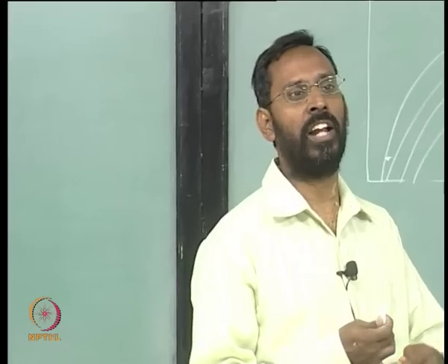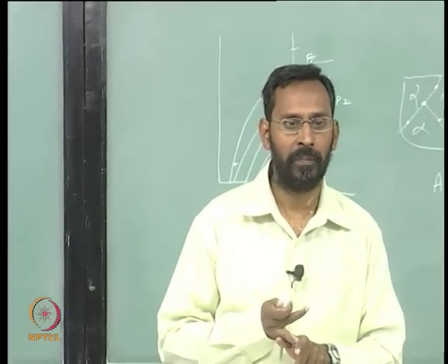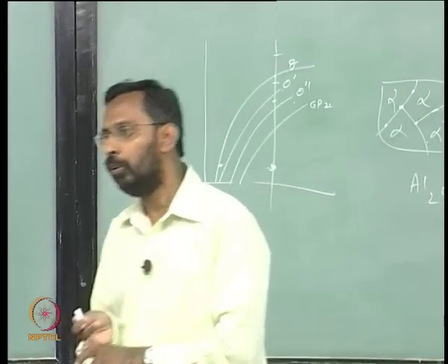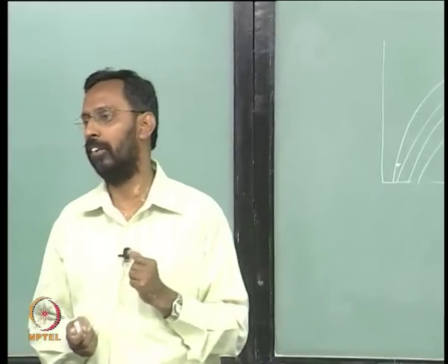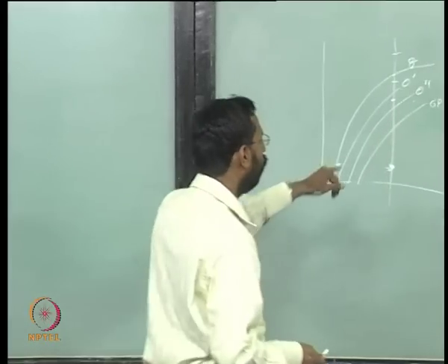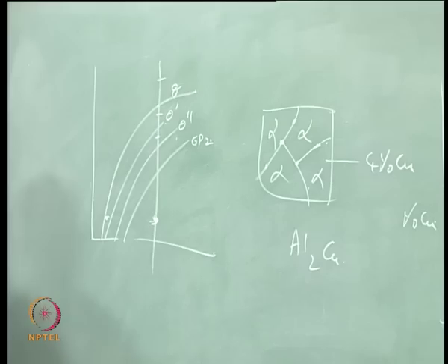When I say lowest energy, it involves both strain energy and surface energy. So, something which can nucleate and grow with the lowest combination of strain and surface energy is the one that would nucleate among the phases that are possible.